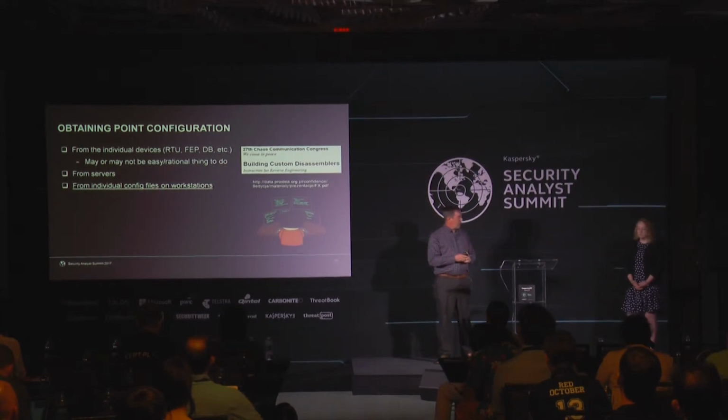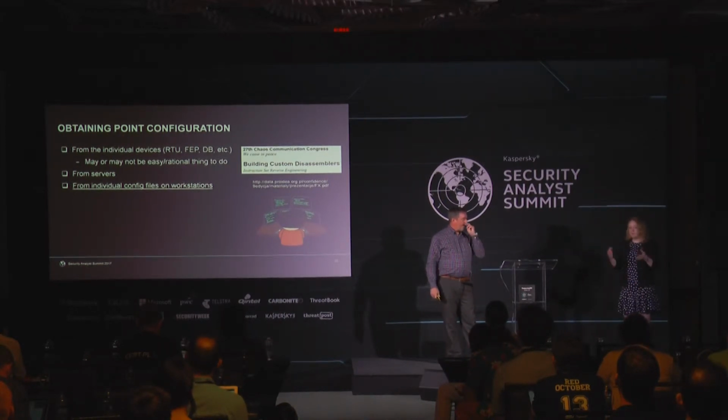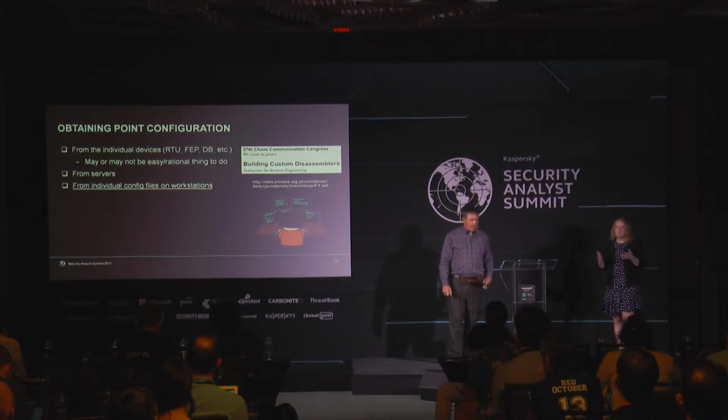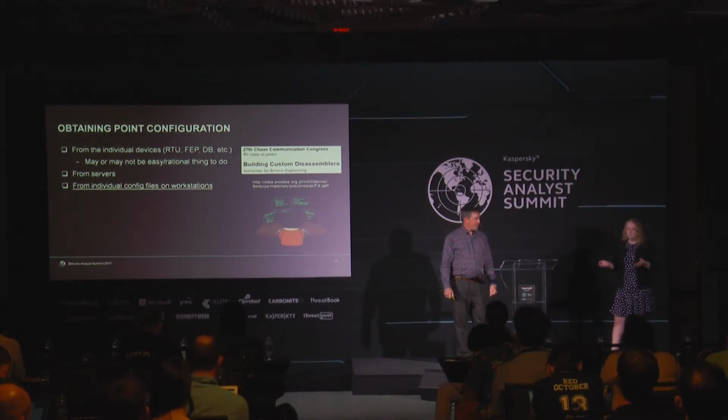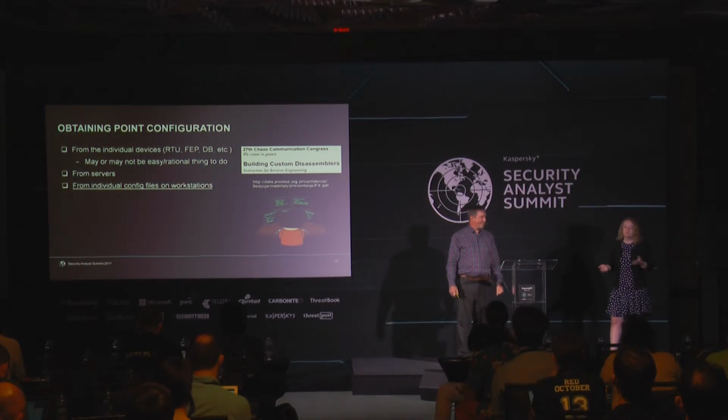Marina, you went to the 27th Chaos Communication Congress. Yeah, so for example, if you try to fetch the config from the embedded devices, sometimes you may be able to log in and see some numbers, but sometimes it will be already compiled binary, and so it will be a proprietary compiler, and we don't even have disassemblers for them, so it's very difficult to build customized disassemblers, but it's not impossible. So, for example, Felix Lindner presented how he built a compiler for Siemens PLC binaries. So it's possible to do that. But because of the multi-vendor culture, it doesn't scale. This approach doesn't scale because you will have to develop custom disassemblers for a wide range of equipment. So basically, getting config from these low-level devices like RTU and so on, it's really not a good approach.